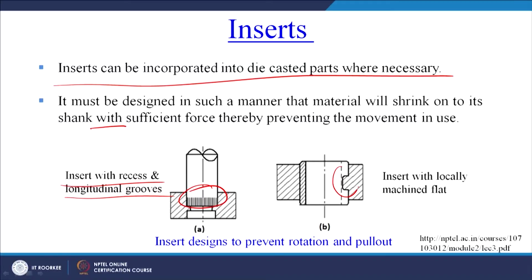So this is an insert with recess and longitudinal grooves. These are the grooves shown here. This is the insert with a locally machined part. So there we have to ensure that the insert fits in the metallic part or the metallic product properly so that there is no movement at any later stage.